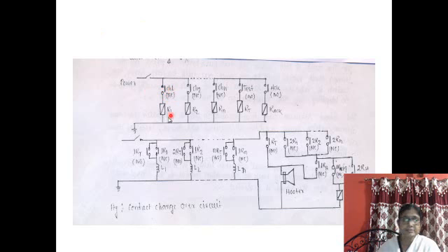As this is in closed position, relay R1, this is another relay operated by this switch. That means, see, this is just an electrical device, one side connected to the ground and the other side getting power through this contact. So only when this contact is in closed condition will this relay be energized. And the contact is closed whenever the particular channel is in healthy condition.